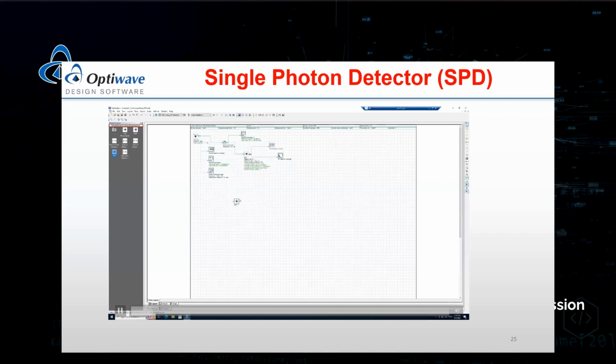This is great for applications in quantum key distribution protocols, non-line of sight underwater channels, or just any application that requires very low receive signal power. You can use this component to do photon counting and time tagging, as well as conversion of light to electrical pulses for further processing and calculation, such as bit error rate.